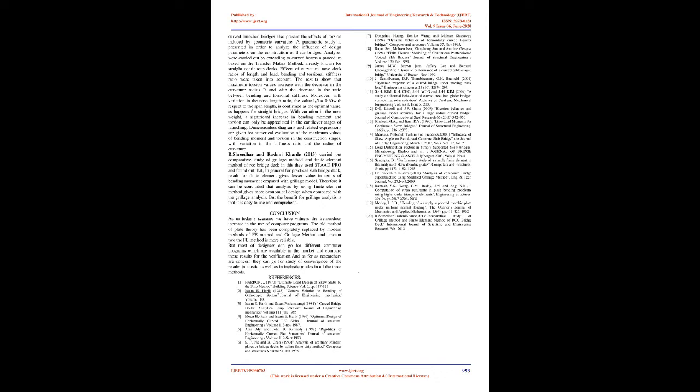Michel Fabio Granata, Piercarlo Margiotta, and Marcello Arisi, 2012, conducted a parametric study of curved incrementally launched bridges, and they found out that the structural behavior of incrementally launched bridges in the construction stages depends on different parameters involving deck, nose, supports and guide devices, because static schemes vary continuously with the advance of the deck above the piers.